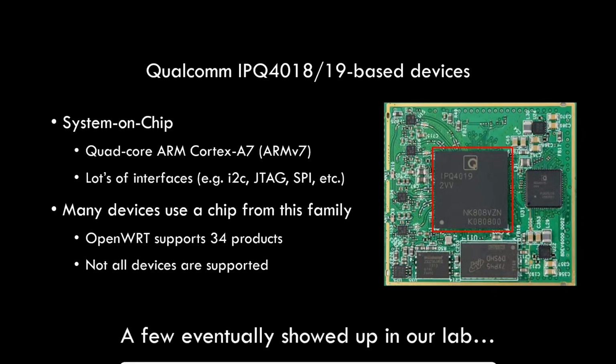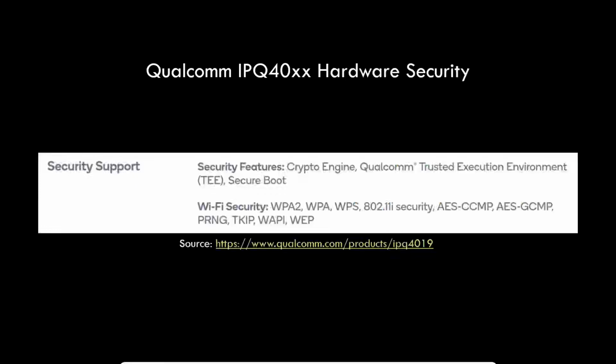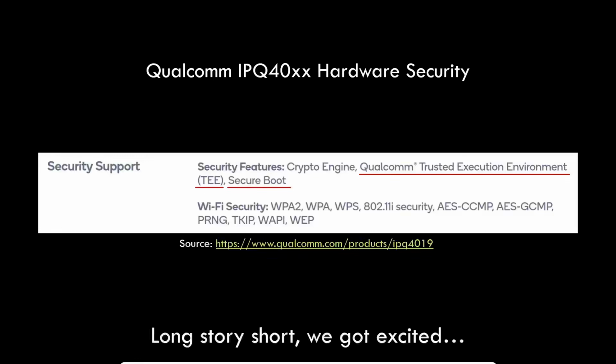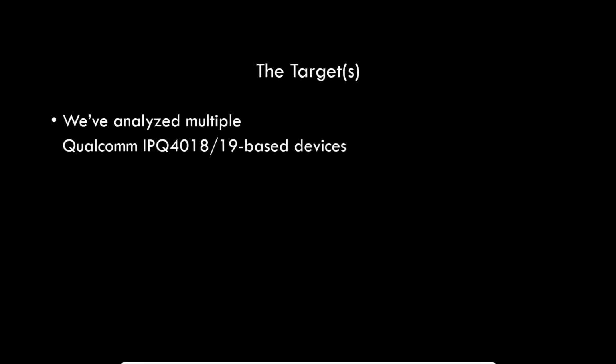So basically, a few of them eventually showed up in our lab. And we got hooked, we got interested, because the security features that you see on the screen are actually quite uncommon for a networked device. You will see that you have a Qualcomm trusted execution environment. There is also support for secure boot, even a hardware crypto engine. And so this actually made it interesting for us. Long story short, we got excited and wanted to look a bit deeper into devices based on the SoC.